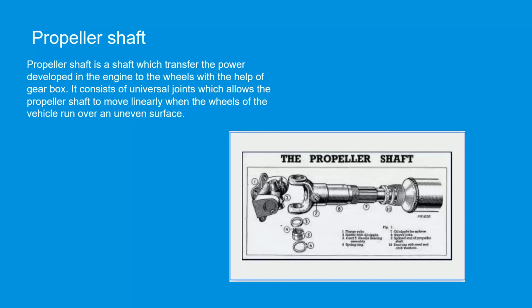As torque carriers, drive shafts are subjected to torsion and shear stress equivalent to the difference between the input torque and the load. They must therefore be strong enough to bear the stress while avoiding too much additional weight, as that would increase their inertia.